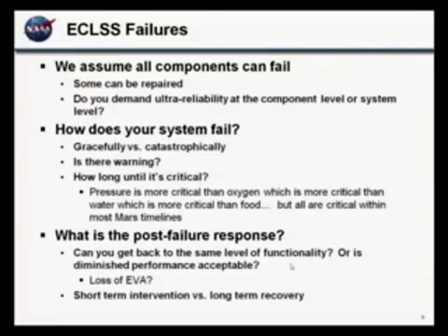So do we on space station. They're both electrolysis. Everybody has tanks of oxygen. That's dissimilar redundancy. And then you have your oxygen candles, which are going to not require power, not really even require control. When you turn them on and start that reaction, oxygen is coming out. So if your sensors are down and your valves are all stuck, you're still going to get oxygen out of that candle.